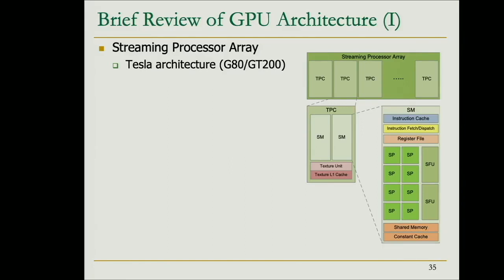This is something like the internals of each of the cores of the GTX 285. You can see that inside this one, what we have is 8 of these SPs, 8 of these SIMD lanes. So what do we need to do to execute one warp of 32 threads on top of these 8 lanes?